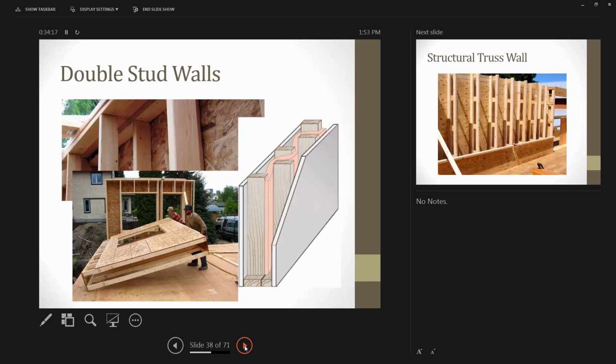They've got an inner wall and then an outer wall, so that inner wall is either going to be that heavy gauge steel or concrete, and then they're going to have a skin on the outside, which is going to be their thermal envelope. And the whole concept, again, is to make that uncoupling of the inside to the outside, back to the basics of what a building does. It separates the inside to the outside, so the more separation we get on it, the more efficient it becomes.